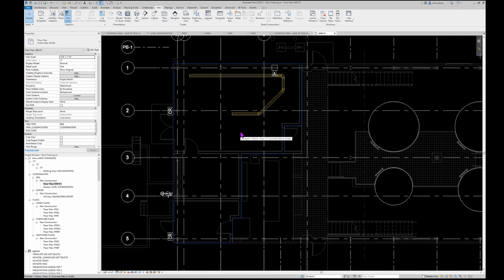Generally, as far as Revit's concerned, this is basic software. It's just a list of elements. You have to go out of your way to add stuff, but it's not going to just blow up because you took one element away from that list. Let's use an architectural perspective: you put all these things in here and you put a door in here, but the door wasn't part of the set. The door is not going to automatically be consumed by it because everything else around it was. Same thing if you redid your pipe fittings or elbows, because they're considered new elements when you do that. But they won't take away from the list of elements that you did do.